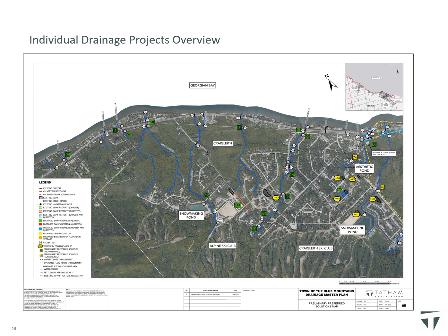Although minor drainage system improvements under Alternative 3A are included in the general recommendations of this study, 2 critical projects involving the decommissioning and relocation of existing drainage infrastructure on private property were identified and included as individual projects. These 2 projects include decommissioning the existing historical Beaver River flume in Clarksburg and relocating the downstream storm sewer off private property into the municipal road allowance. Preliminary designs were completed for these 2 projects, and the individual project evaluation determined that both of these projects are recommended for inclusion in the preliminary preferred solution.